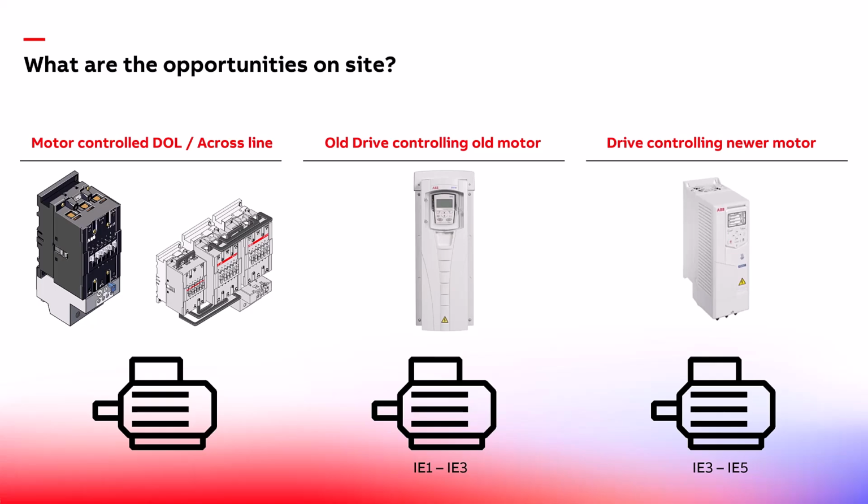As you can see, the IE3 to IE5, what I would class as newer motors, I'd say IE3 is probably the crossover point round about the middle, and we'll see a bit more of that on the EcoDesign slide. But IE5 to IE6 is where the motors are pushing now for the highest efficiency.